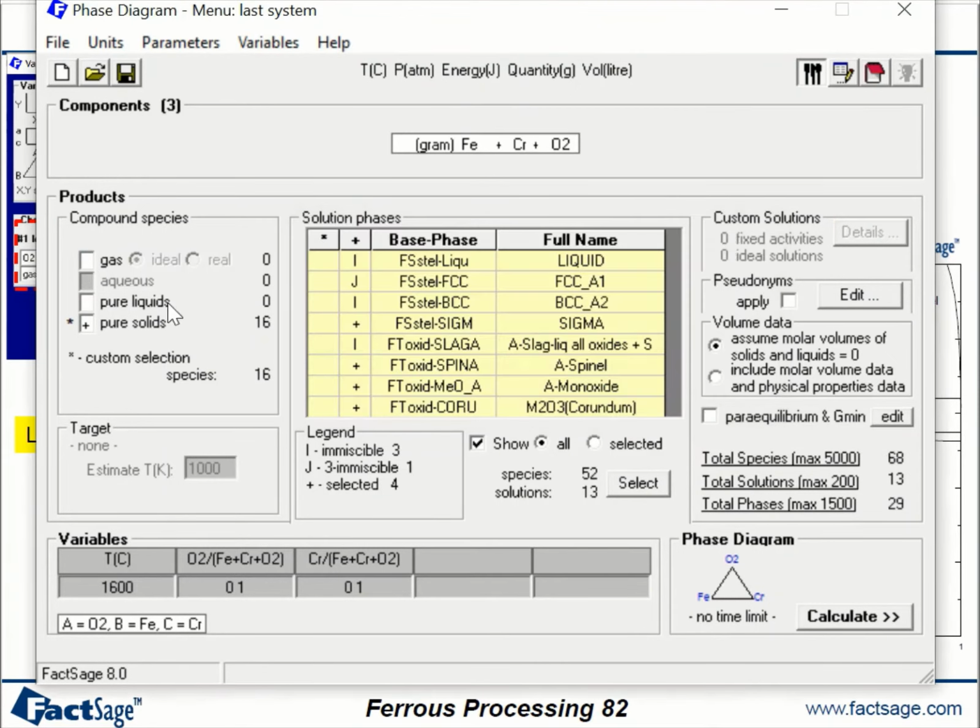But in most of the calculations, when we do PO2 with something, you don't have to select this gas phase, because we are not producing the gas phase in the calculation. We simply set the gas partial pressure, and because we set oxygen O2 as the gas partial pressure, it will be changed automatically without really producing the gas phase on top of the metallic phase. Do you understand what I mean? So we just virtually control the partial pressure of oxygen, and then we calculate what kind of phase can be formed at that virtually fixed partial pressure of oxygen.